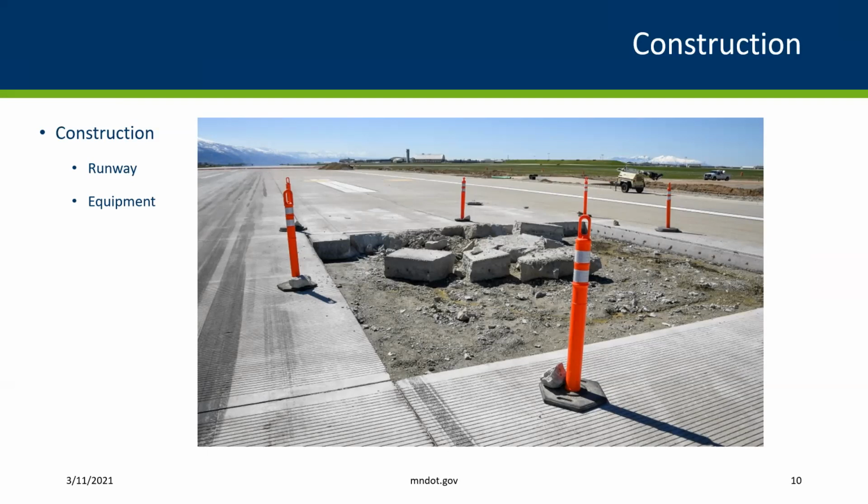That NOTAM goes away, and at that point, if I were just looking at the NOTAM and I'm not familiar with the airport, traveling in from out of state, there's absolutely nothing to indicate any construction. So if you have projects going on and they happen to run long, that's a big cue, as an airport operator, to make sure your contractors are keeping those NOTAMs up to date, and that if they expire, they put them back in until the project is complete.